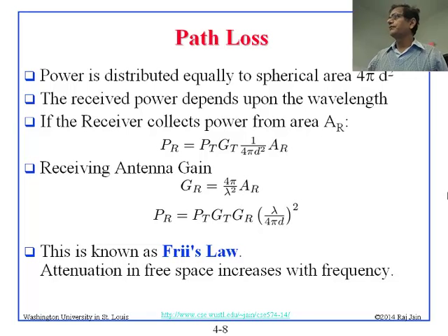This is the formula. Basically, you multiply all of this, and that is called the path loss. So you send some watts, and you get some other watts, and the rest is the loss. This multiplier is the loss. We will be doing all of this in log scale, so you have some dB power sent and dB power received. The difference would be the path loss.